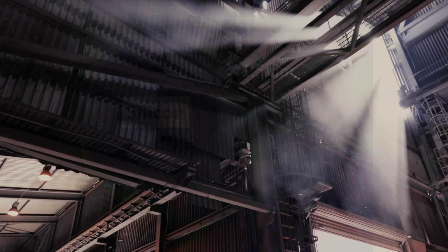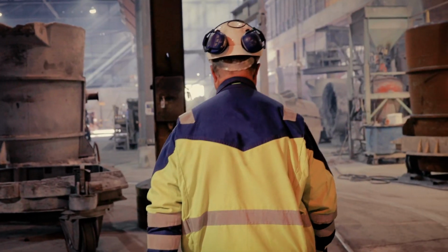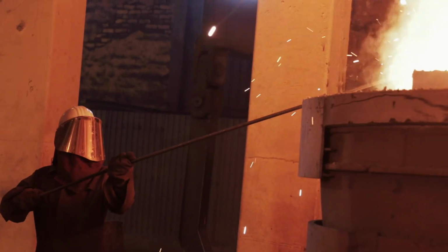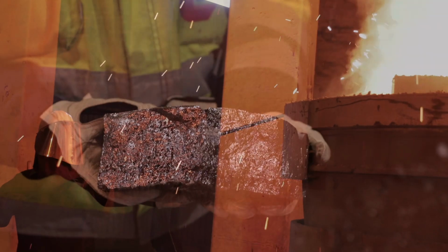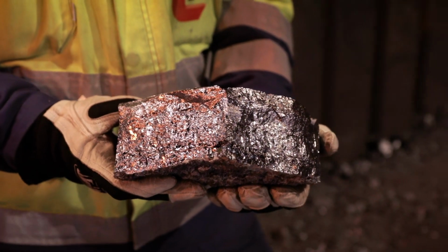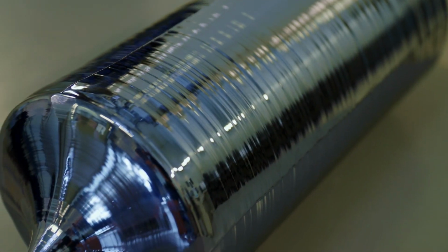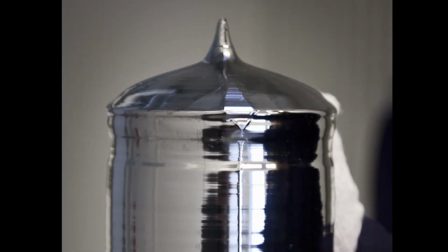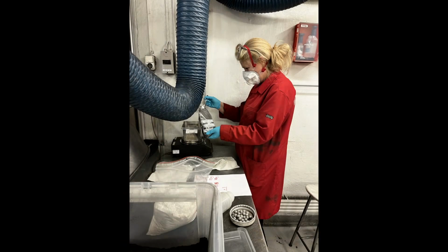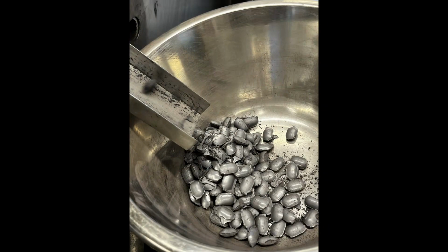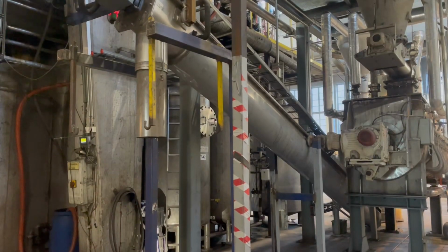The results obtained during our waste inventory reveal the contamination levels, composition and morphology of silicon kerf and provide insights relevant for subsequent processing and refining. For recycling it back into the PV value chain, silicon kerf requires different treatments: drying, cleaning, refining and agglomeration. The cutting process could be adapted to reduce and avoid the contamination by some impurities, which is currently investigated in this project.